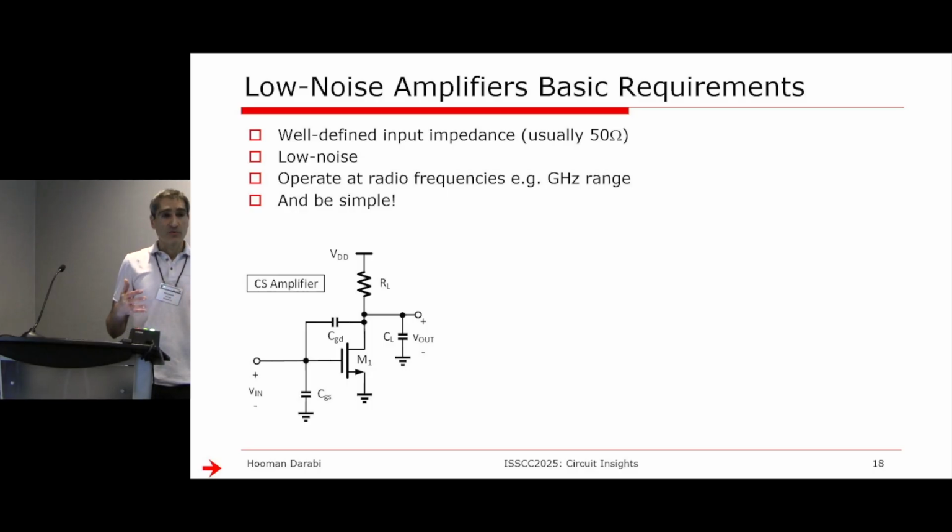Now, this will degrade the frequency response of the amplifier. CGD particularly is problematic. You see small swing here, fairly large swing here because of the amplification. So this lopsided swing on 2 terminals of CGD exacerbates the impact you see at the input, known as the Miller effect.